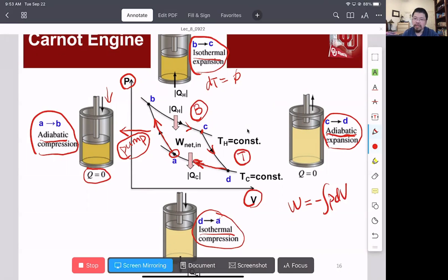Okay, corresponding to the turbine, over there we are going to have the work produced over this unit. And since this is adiabatic, make sure you have that condition provided. Now we are here at D after the turbine, where we are going to have the exhausted steam. Then we are going to have the condenser, moving the working fluid back to the initial liquid state. And of course, along that process the temperature is constant, dT would be 0.